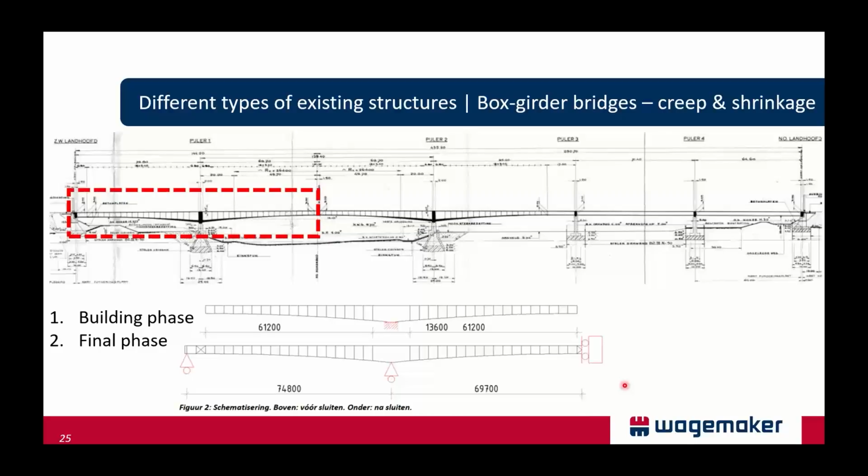And we did first the building phase when it's still cantilevering. And then after that, we put the supports and the closing segments. And in the mid-span, we put symmetry conditions so that it actually represents the whole part of the bridge spanning the river.